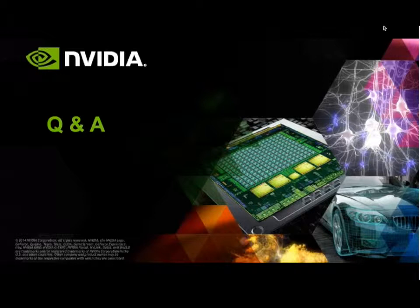It is possible. vGPU currently doesn't support that, but on pass-through, if you're dedicating that GPU, pinning it to a guest, that guest then could in fact run OpenCL, CUDA, and handle some HPC work. Obviously, this is not a replacement for a Tesla, but there are apps that absolutely leverage and do rendering using CUDA, and you can use these cards to do that as well.